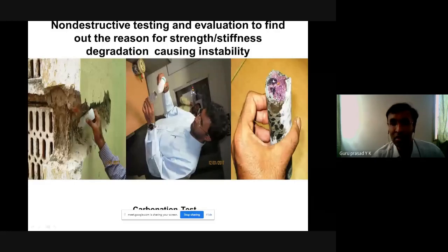If the concrete turns pink, you see this figure here, I'm moving my cursor. Actually it's a core which has been extracted through the core cutting process. I'll come to that. If it turns pink, it means that amount of concrete has not got carbonated. The concrete around the pink portion here is not pink, which means that much thickness of concrete has got carbonated. So if you have reinforcing rods inside here, they are bound to start undergoing corrosion, meaning they'll start rusting after some time.